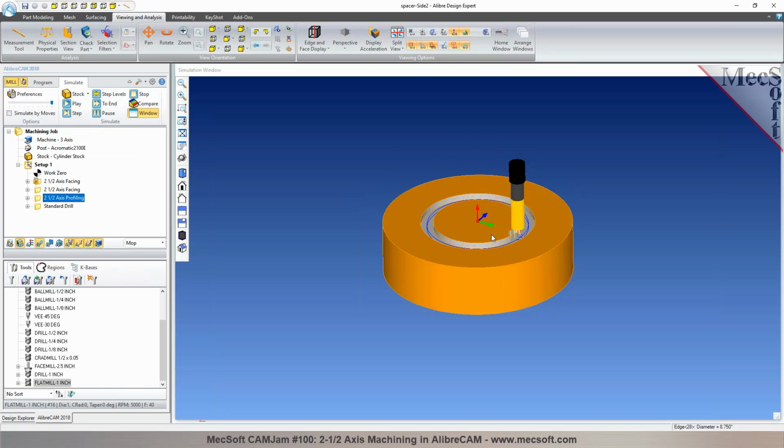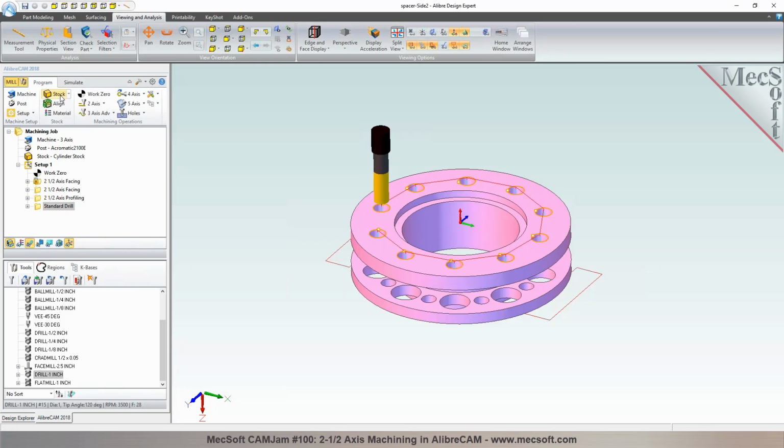So there's the step being cleared. The stock shows that there's still a solid geometry, but since you already had a pre-cut hole in the blank, if you want to define a blank with a pre-cut hole, then you would need to have the professional configuration, which can do stock from selection. So you can actually design what the blank looks like, and you can define it as a blank. So the Pro has additional features, which allows you to define stock from selection, and also stock from extrusion as well.